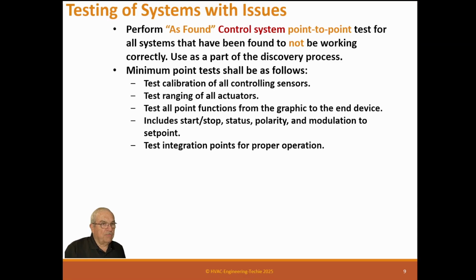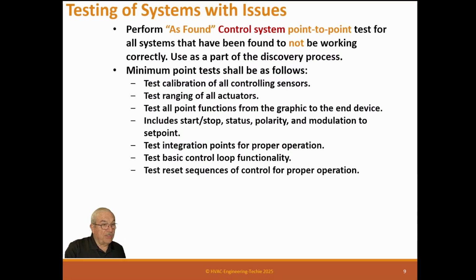Test integration points for proper operation. So if you have a system that's integrated with another system, then you need to check both systems to make sure they're talking properly. Test basic control loop functionality.